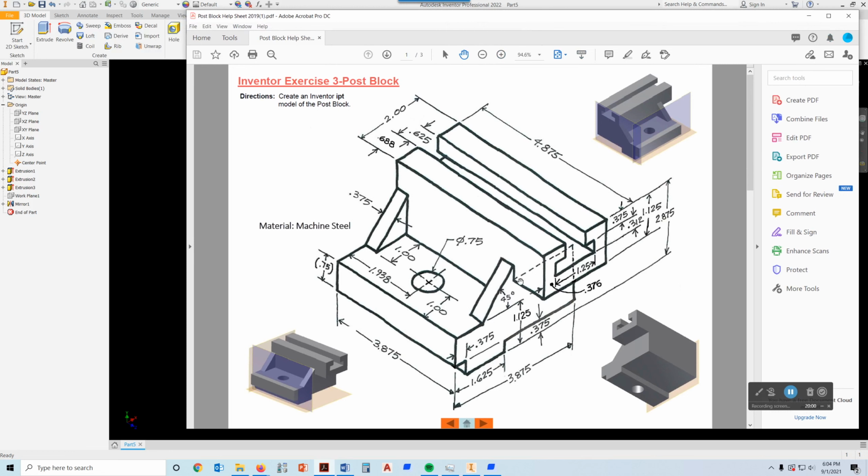All right, so just to go back, first to show you that guy right there, there's the 45 degrees, and here's the 1 inch that we established along the bottom edge here before I extruded that. And then the width of the extrusion is 0.375. So now we want to put this hole on, and this hole is 1 inch from the front, and it's 1.938 from the back edge. Don't dimension from this. Always use the same dimensions if you can. And it says it's a diameter 0.75, and since there's no depth, we have to assume that it goes all the way through the part.